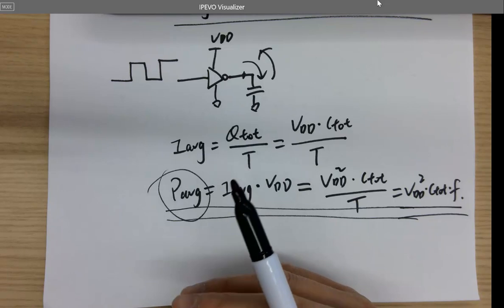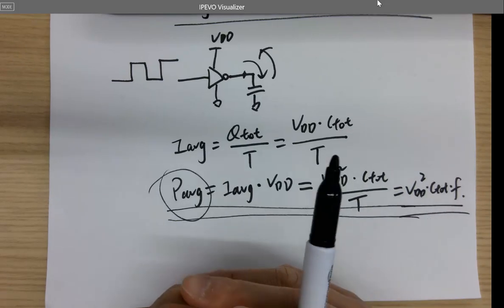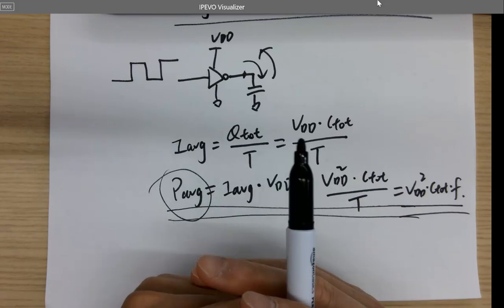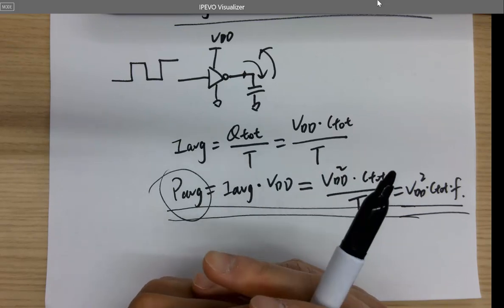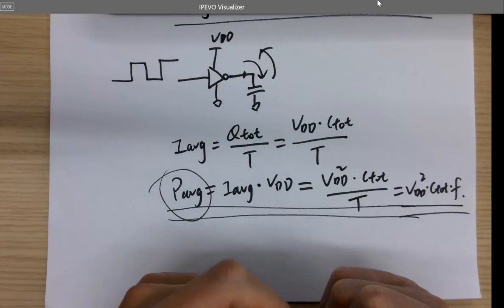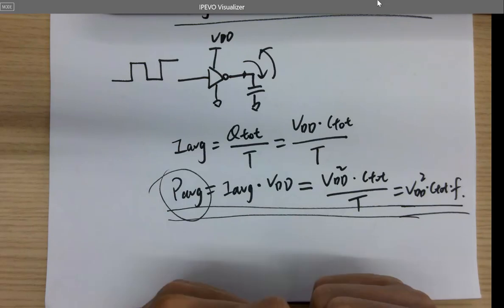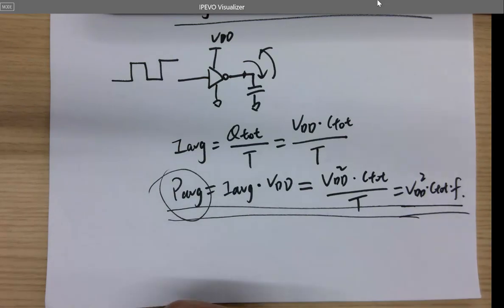You probably saw all different voltages, like 5 volts, sometimes 3.3 volts. And a lot of transistors are running at 1 volt. You probably don't know that. So most of the 180 nanometer from TSMC are able to be driven by a 1 volt VDD. It's amazing.